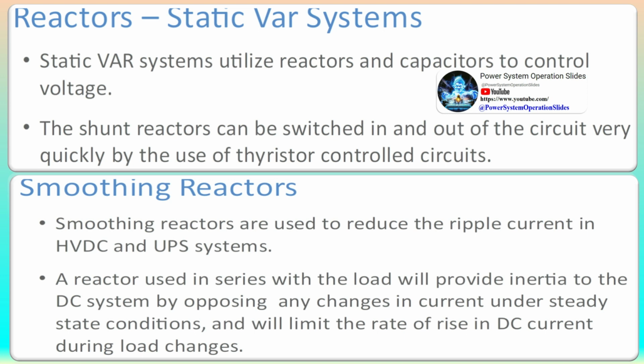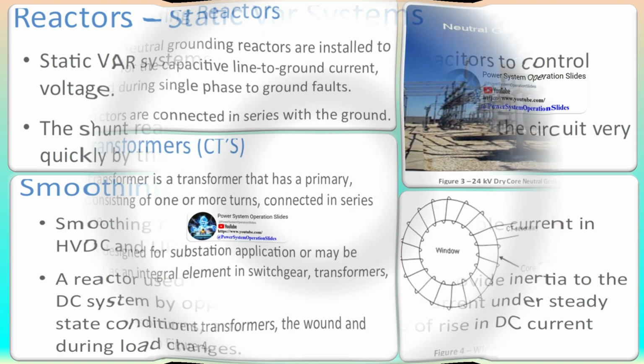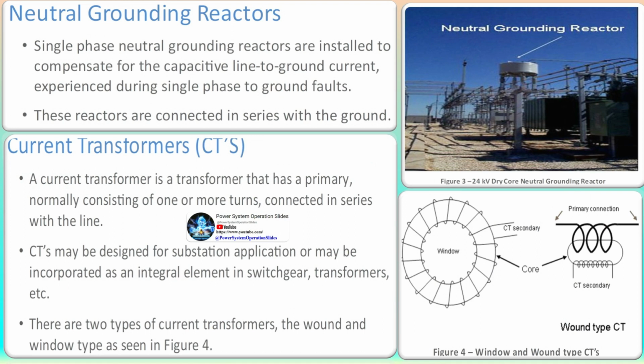A current transformer is an instrument transformer, used along with measuring or protective devices, in which the secondary current is proportional to the primary current under normal conditions of operation and differs from it by an angle that is approximately zero. Current transformers supply the protective relays with currents of magnitude proportional to those of the power circuit but sufficiently reduced in magnitude. The current transformer isolates the measuring instruments from high-voltage power circuits.